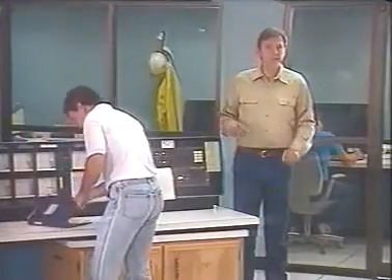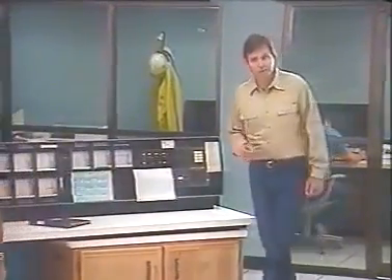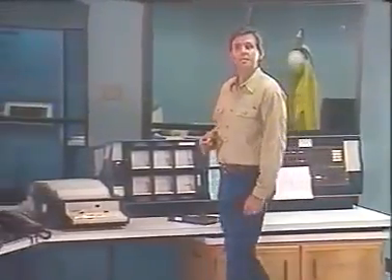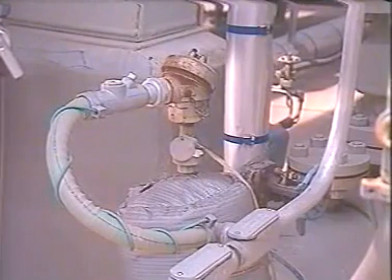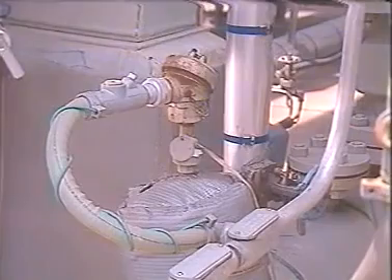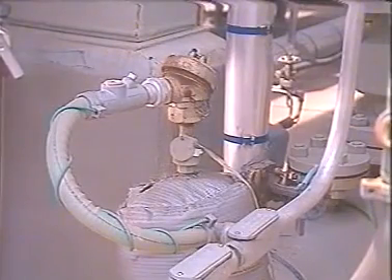We've covered a lot of information in this first instrumentation program. You've learned that controlling a process is a matter of controlling its variables. When we control the variables in a process, we're able to produce products that meet the specifications we want. You have also learned that no matter what the variable and no matter what the control situation, four basic elements are usually needed. First, there is a process that needs measurement and control. There must be one or more instruments as a measuring means that senses and measures the variable being controlled. The measuring means also transmits a measurement signal.